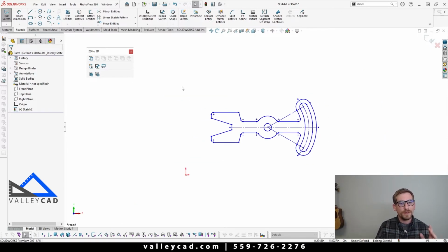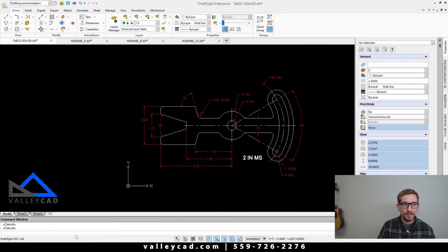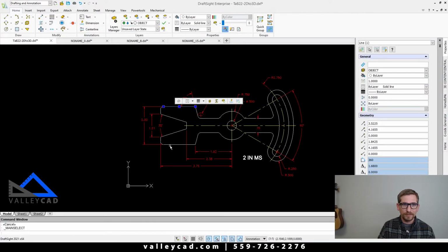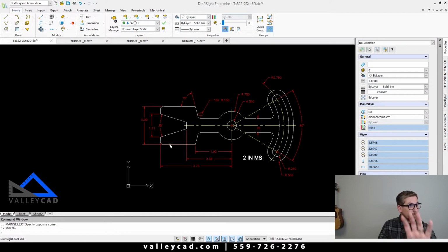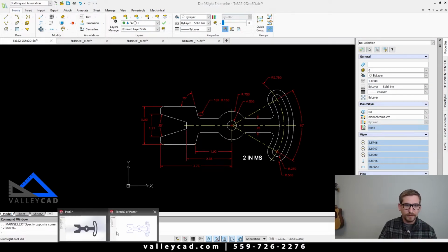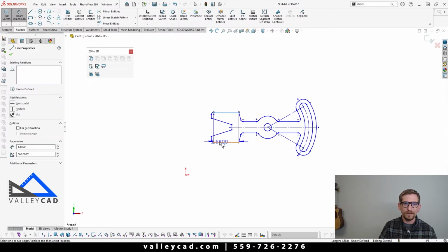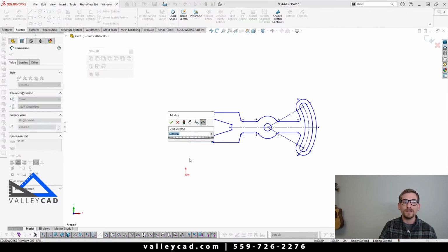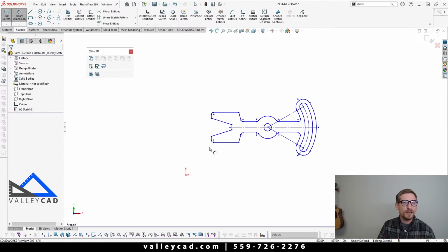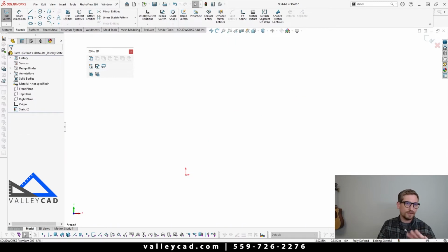And by the way, if you notice here with that dimension of 2 inches from here to here, well, if this was modeled in a scale of 1:1, coming back into SOLIDWORKS here, smart dimension from here to here, just to verify, you'll see it also shows 2 inches. Pretty awesome there, by the way. All right, so we'll simply delete that. And what I'm gonna simply do is do a window and delete the entire thing.